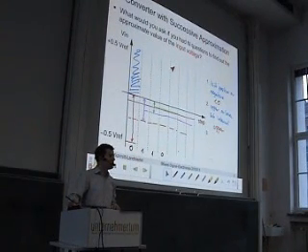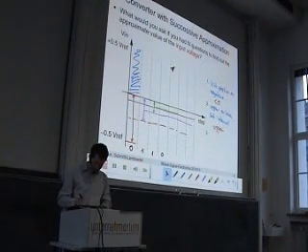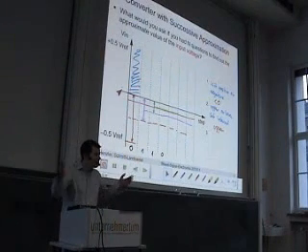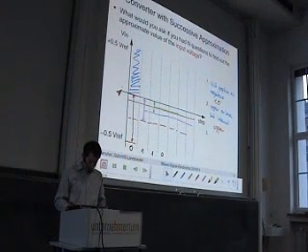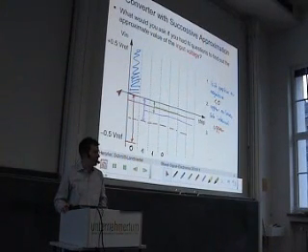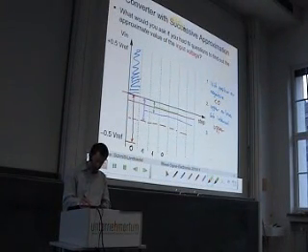This is what we called the offset coded representation of this. And offset means that the 0 value here is not all 0, but has a certain finite value, which is here 1 and all 0. So this is the offset that we have here. This converter is called a successive approximation ADC.